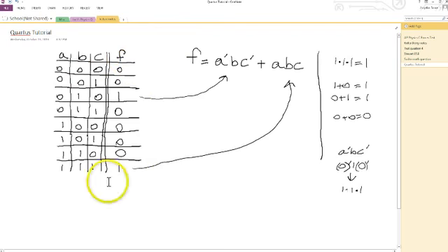So going from the truth table, we would order all of the combinations of inputs we could possibly have. In this case, the easiest way to get all the combinations is to count. So in binary and 3 bits, we're counting from 0, 1, 2, 3, 4, 5, 6, 7. And I've just randomly chosen an output that we'd like, but when you build your 1-bit adder, you'll use the concept of binary addition to determine what your output should be.